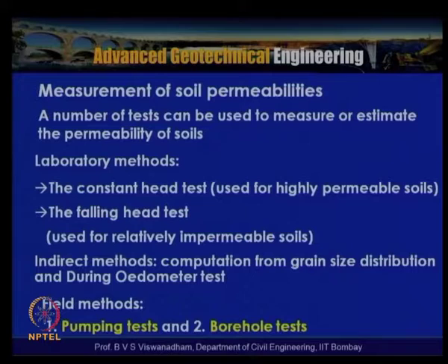As mentioned earlier, there are indirect methods, some correlations which are available based on the grain size distributions, that is based on D5, D10 and other particle sizes. Basically for sandy soils, some correlations are available. By knowing the effective particle size, we will be able to estimate the coefficient of permeability.